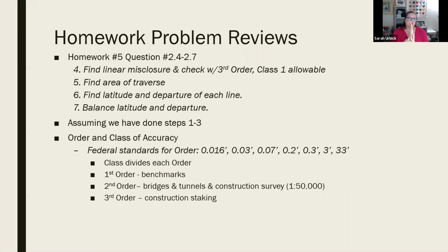Remember, that's measured off a north-south meridian. And then we need to balance the latitude and the departure. So if we have an error in our closure, we need to spread that back amongst all of our readings to say, okay, proportionately, this is really where we are, okay? So assuming 1 and 3 are done,